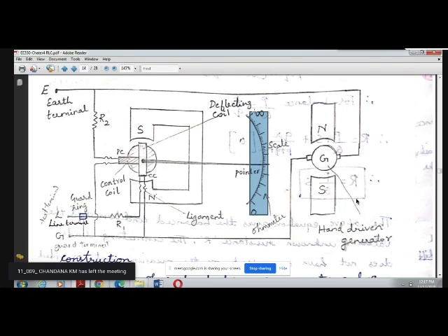Since it is open circuit, the resistance value is infinite. So you should get infinity. The pointer, which is initially in the middle position, should move towards infinity. This indicates that the megger is working properly.